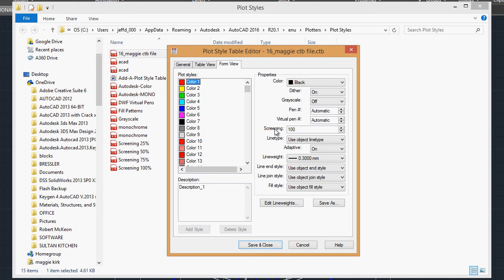Another thing to watch out for with screening is that the gray line might show up when you go to print, printing over the black line. So this can be controlled using the command draw order. If you select your gray screen line and go to the options of the draw order command, then you have the option to bring the lines or objects in front or behind the other lines and objects individually. So note that this will work with any object, but if you're printing all the lines black, then it's nothing that you really have to deal with.